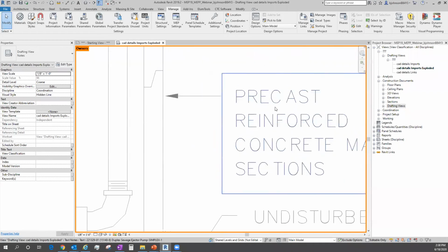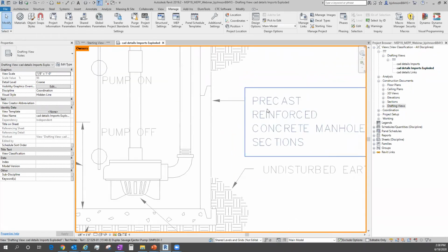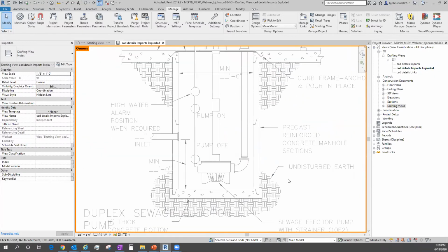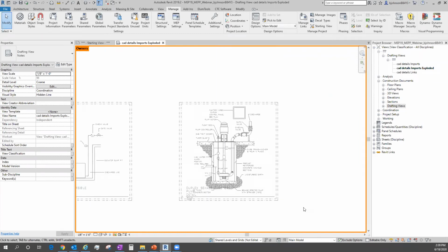So we're not using fonts from AutoCAD, which don't plot very well most of the time. The old field regions, the hatch patterns for the arrowheads that come from the leaders, those are individual field regions in Revit. So little things like that we want to avoid using if at all possible. Keep our drawings clean and understand how they're working, and do some mentoring for people who are not aware of what the standards should be.